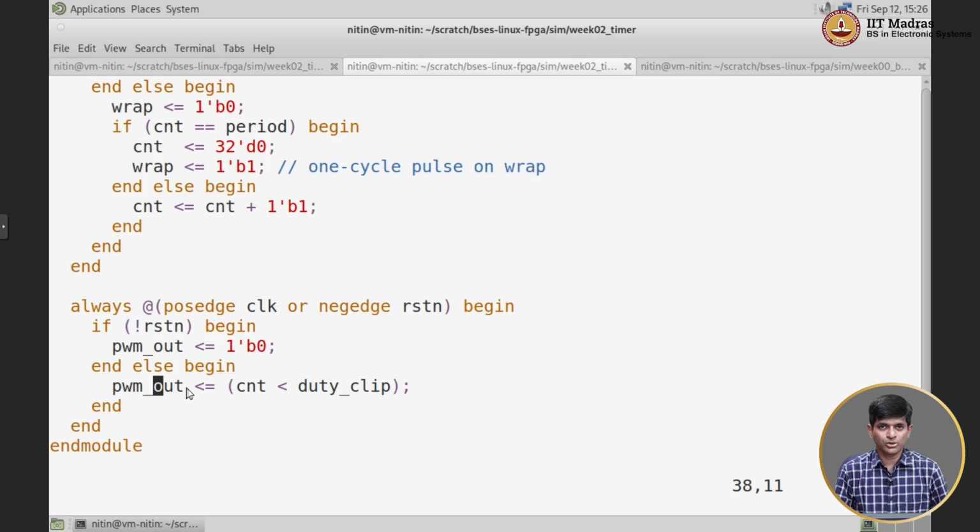Now what we want to do is, this module by itself has absolutely no software interface, right. The only way to use this would actually be to connect a clock, the reset, the enable signal, check the value of PWM out, set the value of period and duty cycle as 32-bit values directly, right, which means that you could do that if you were wiring it up somewhere, directly connecting it to some other hardware modules inside an FPGA. Yes, this would work fine.